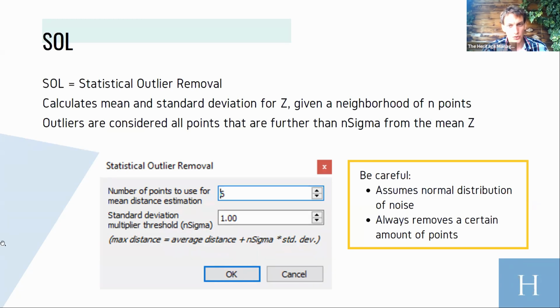This is not a very useful technique to implement when you're working with hardcore 3D data, so 3D data of a facade, for example, because under normal circumstances, it will only consider the Z value, the elevation value of your point cloud. But this is very useful if you're working with bathymetric point clouds, with airborne point clouds, or with point clouds where you have a facade, but the facade is put on a flat plane, like what we did when talking about the photogrammetric project in Ghent.